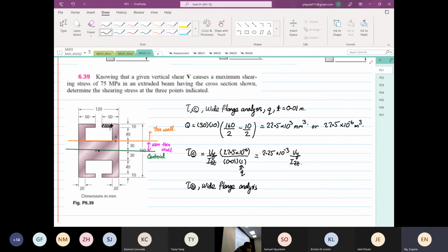If we were to draw our shear flow, it will go this direction. Remember, we drew the shear flow. Why I deliberately want to draw the shear flow down here is because then you know what thickness to take. The thickness is perpendicular to the shear flow direction. So for this case, the thickness is this direction now. Anyone, anything not clear, stop me now, you ask now.